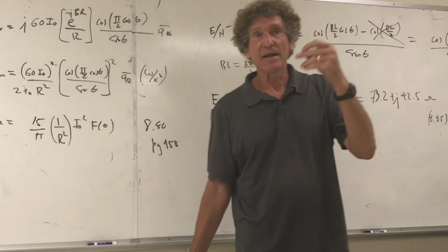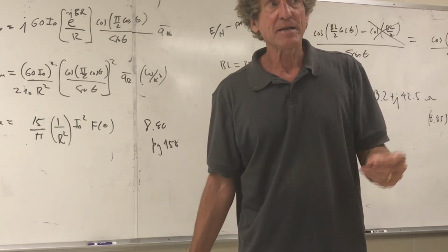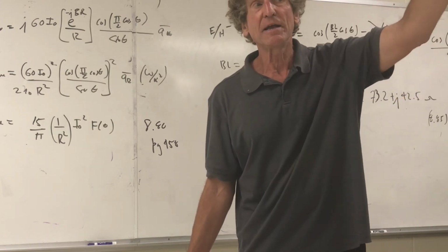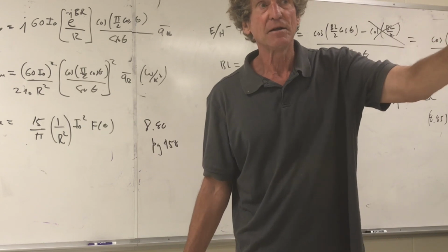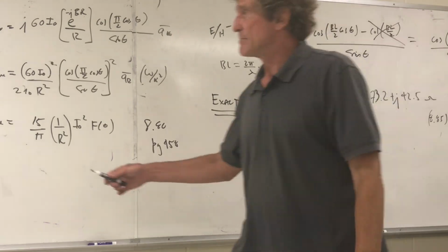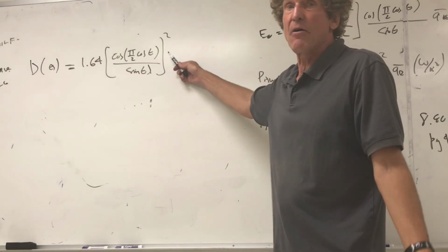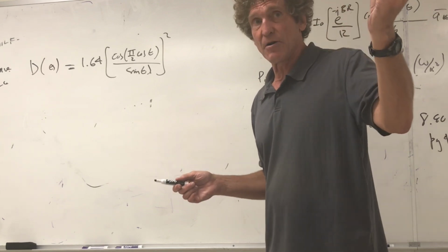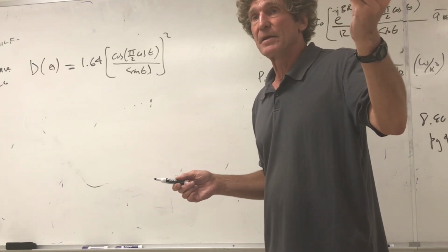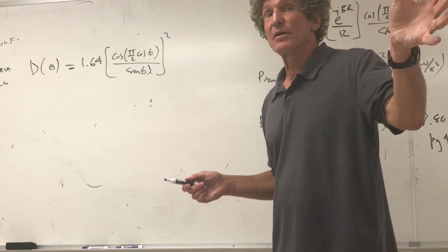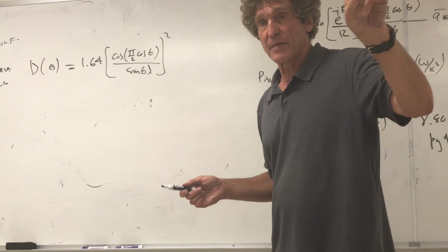Now, once I have the radiated power, if I want the power density at any point r, theta, I take total radiated power divided by 4 pi r squared. That's the isotropic power density. Then multiply times this, we're assuming no loss, and now I have the enhancement factor. How much power density is out there, y'all hear me? To get the electric field, find that power density, set it equal to 1/2 times E squared over eta. I can figure out the electric field from that. Y'all with me, class? All right, guys.